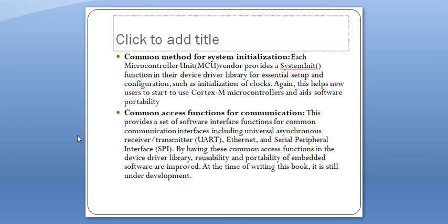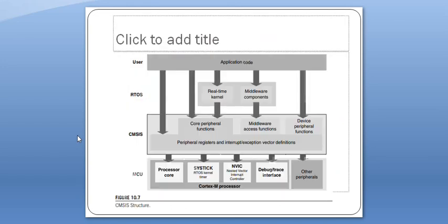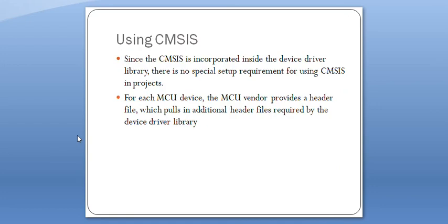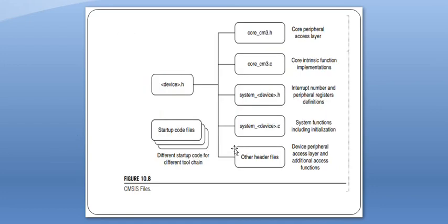Okay, so that's what you have today. For the time being, a few things you can take note of in the CMSIS file. This is important: the device file, startup code, and the core CM3 file, CM3.h file as addressed, interrupt numbers, everything, all peripheral related register definitions you will have in this device.h file and device.c file.